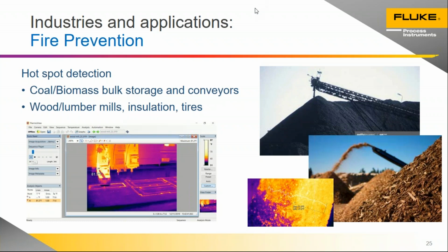In this application, we were at a biomass plant, which was using wood chips, just like you see here, brought in by a conveyor, put into a large hopper, and then using big screw presses, they moved that material down into the boiler. And the problem they experienced is that these wood chips sometimes, especially due to the friction from that screw press, would catch fire in a place that they shouldn't, which of course results in a fire situation and a shutdown of the plant and an inefficient situation. So they were looking for a means to monitor that.